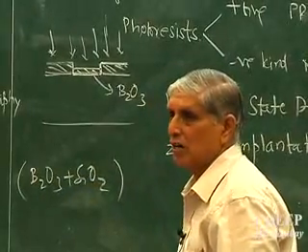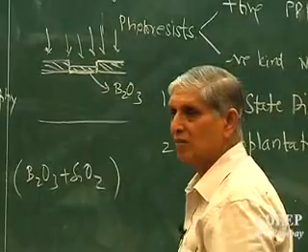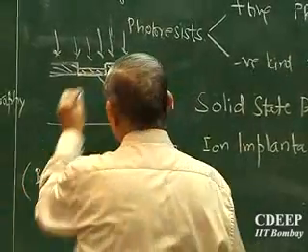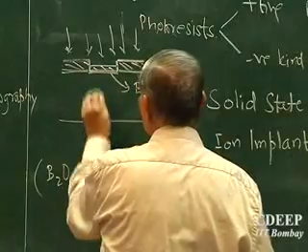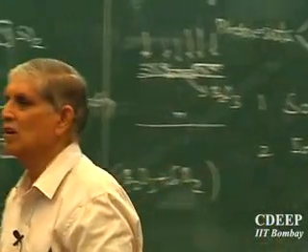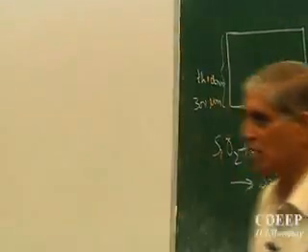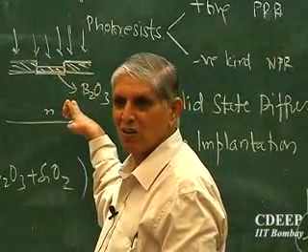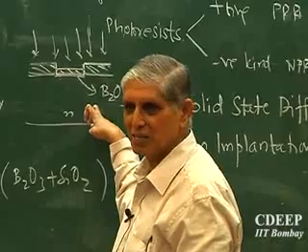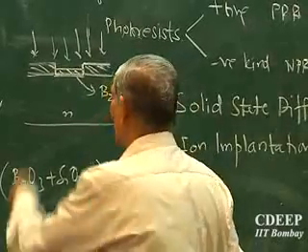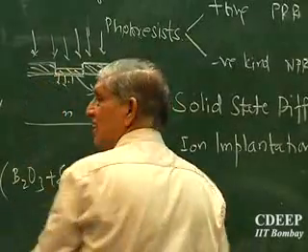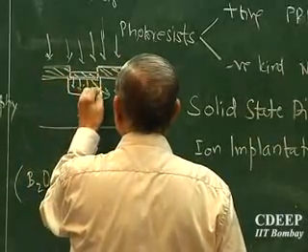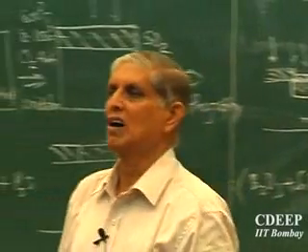Now, if I heat the wafer again in nitrogen, this is how the process of diffusion would come. This contains boron, and what does this contain? Very few holes, meaning practically no p-type. So what will happen? Large concentration of boron at the surface, very little concentration in the substrate. So what will it do? It will do diffusion. So impurities start diffusing down. The time and temperature you choose decide how deep they can go, and it will create an area which is p-type.